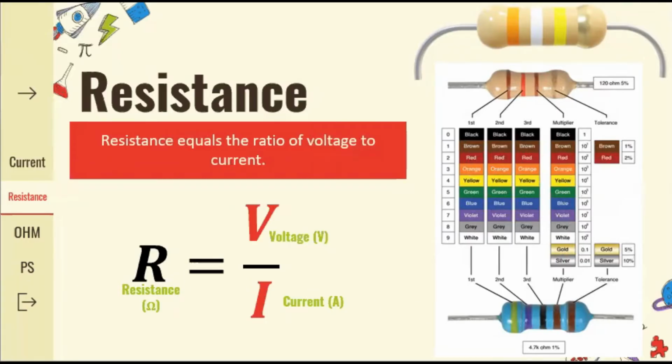So the resistance of an object doesn't limit lang sa mga resistors. Even our skin, yung katawan po natin as a human, meron din po tayo individual resistance. Under dry conditions, the resistance offered by the human body may be as high as 100,000 ohms or 100 kilo ohms. If your skin is moist or it is wet or broken, it may drop your body's resistance to 1 kilo ohm. Adding that, high voltage electrical energy quickly beats down human skin, reducing human body's resistance to 500 ohms.